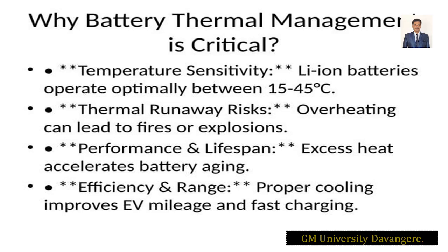All right, the next is the lifespan. When you talk about the lifespan of the batteries, excess heat can cause battery aging also, right? So the batteries shouldn't overheat, because the enormous heat produced in the battery will degrade the battery's life, and aging will also happen. Then you have to replace the batteries within a span of 2 to 3 years. If you have taken a 5-year guarantee, you would have to replace it by 2 years if you don't monitor the temperature of the batteries, right?